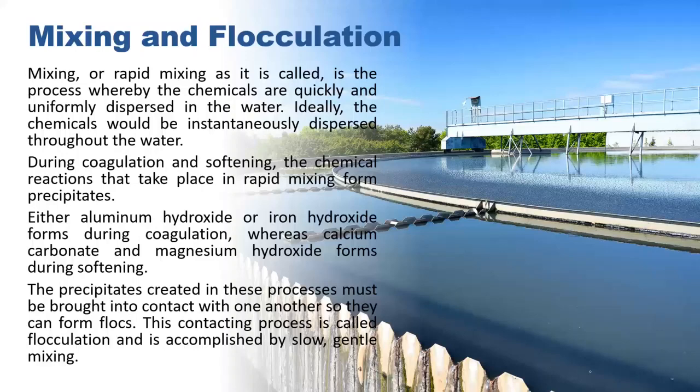The precipitates created in these processes must be brought into contact with one another so they can form floc. So floc is formed after coagulation. This contacting process is called flocculation and is accomplished by slow, gentle mixing.